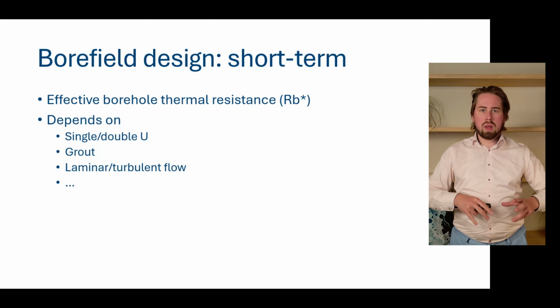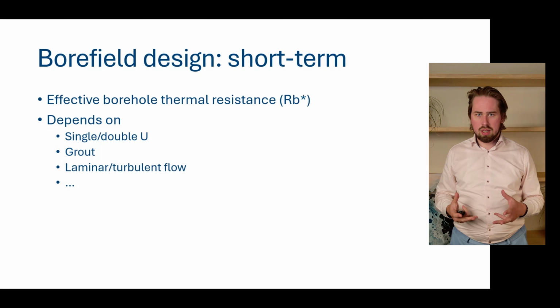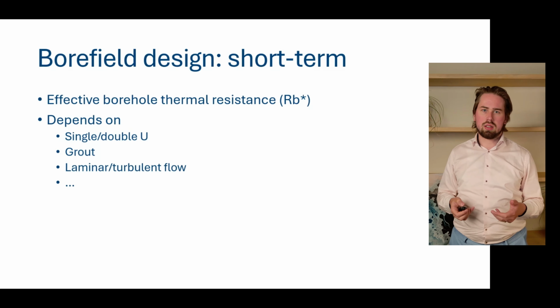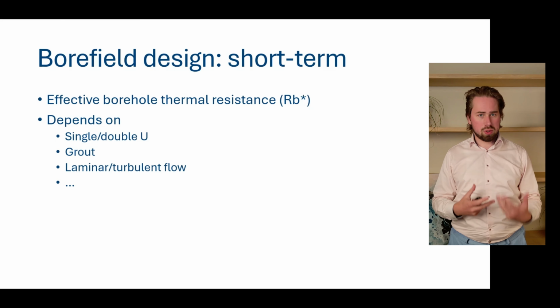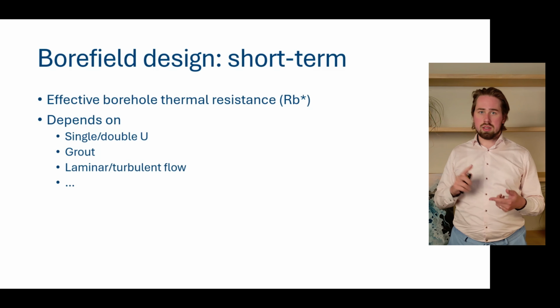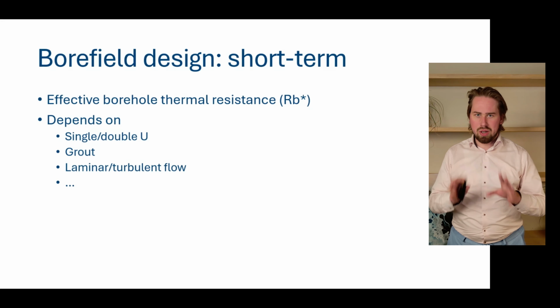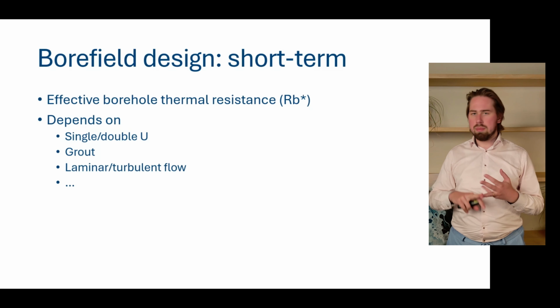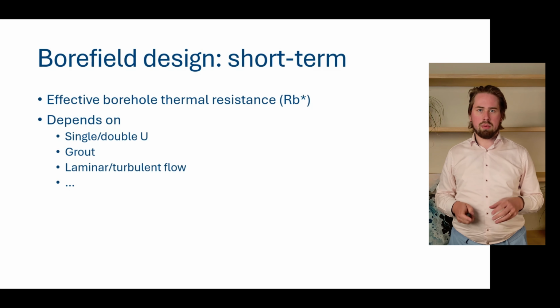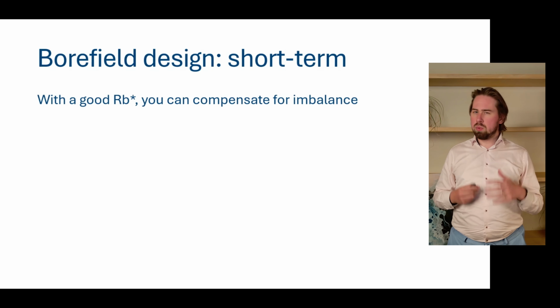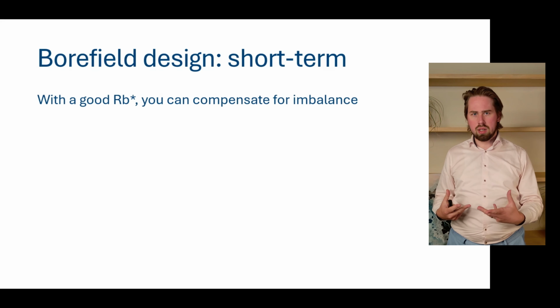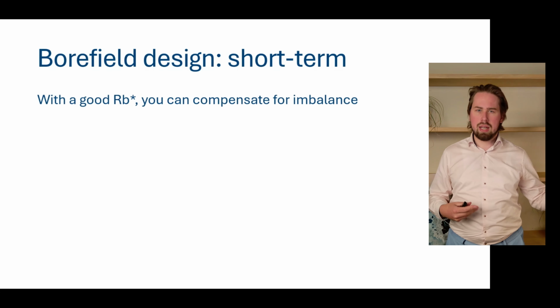Now, on the other hand, we have everything related to the short term. Now, the short term, as discussed already quite a lot of time, has to do with the effective borehole thermal resistance, and this depends on single or W tube, as you now know everything about the grout, laminar and turbulent flow, and all these type of things. Now, the philosophy here is, why do we care about the short-term effects when we're talking about the imbalance, which is something on the long term?